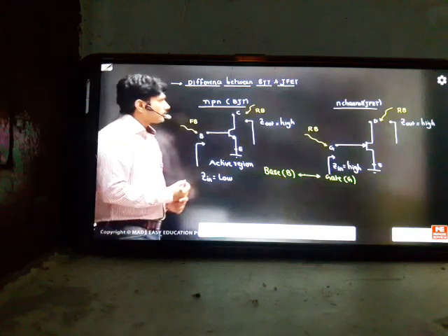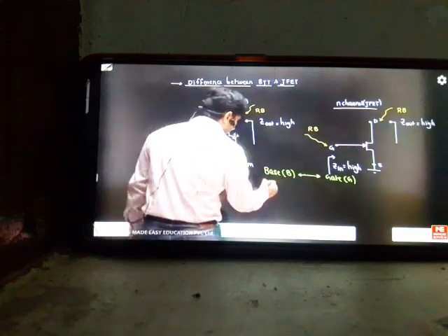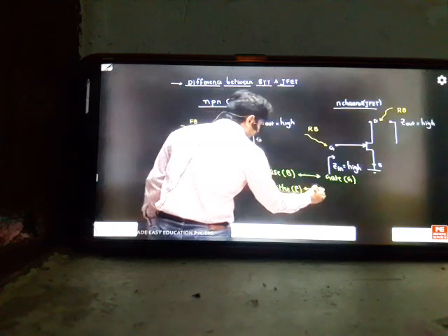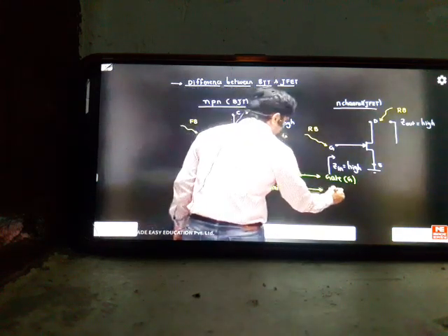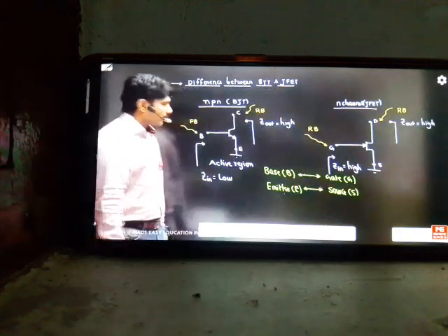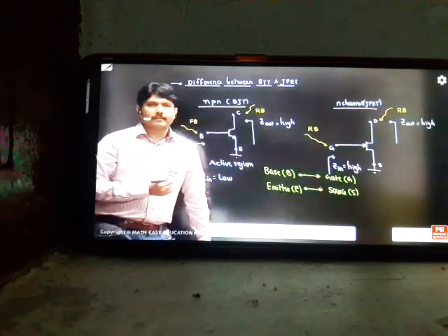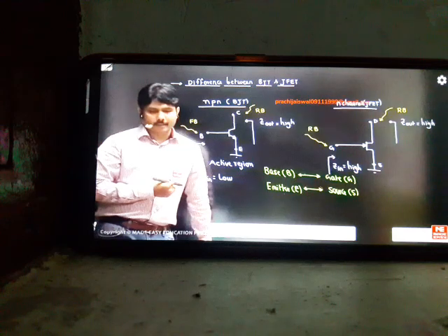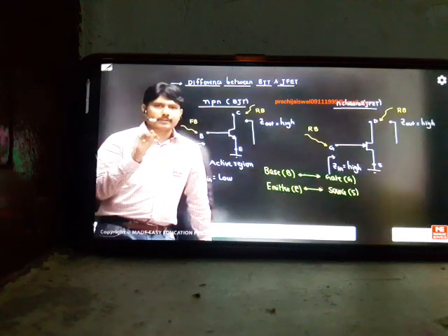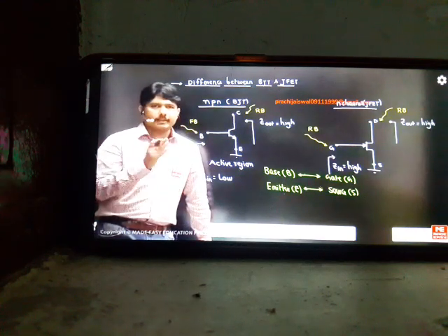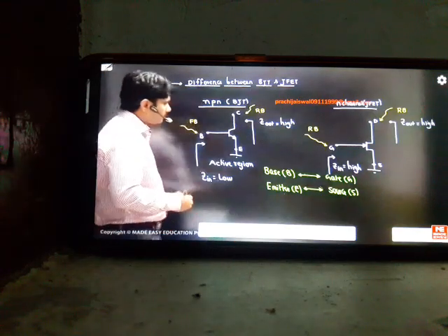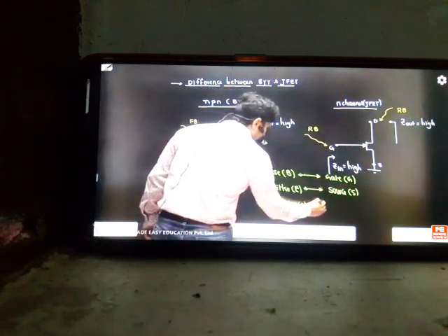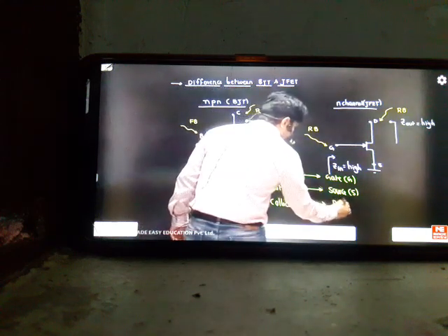Okay. Next we'll see another equivalent, the emitter. If you see here in BJT, emitter E, the equivalent for this is the source. So source is an equivalent form of emitter. In analog electronics, that's why a common emitter amplifier and a common source amplifier will perform in the same manner. Whatever applications you have for common emitter, the same applications will come for common source amplifiers in the next classes. So the source is equivalent to the emitter, and gate is equivalent to the base. Okay. And last we have one more: the collector. In BJT class, whatever collector we have is equivalent to the drain here.